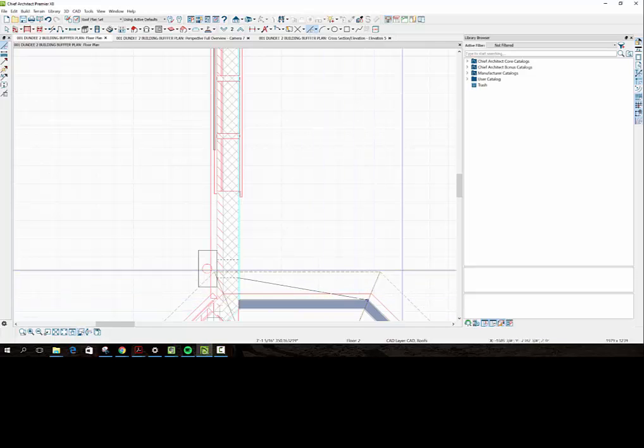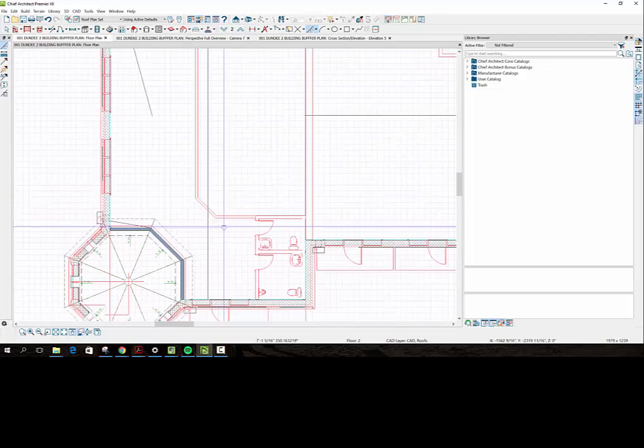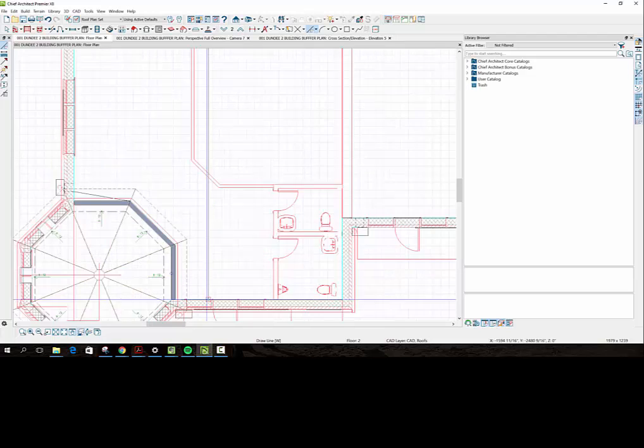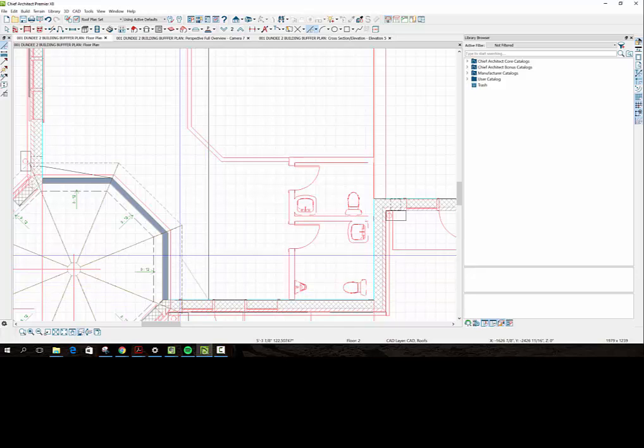So the water goes bonk into the downspout from this high point. Now it's going around the horn, bonk, right there. And we're going to have to get it around. Now it's going down here, dying into this wall. So we got to direct that water that way. So we're going to need a cricket from there and there. And that cricket is directing the water this way.